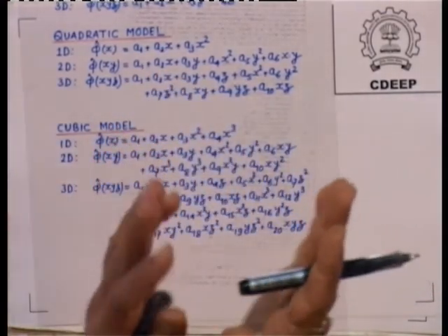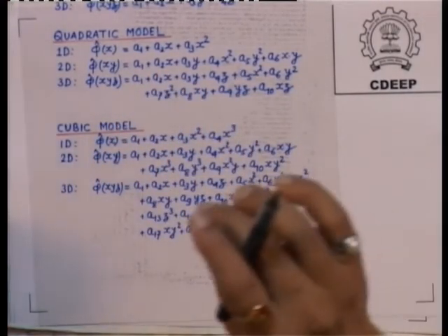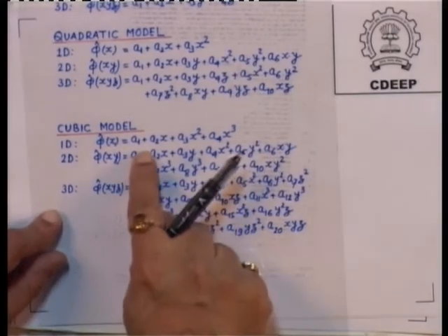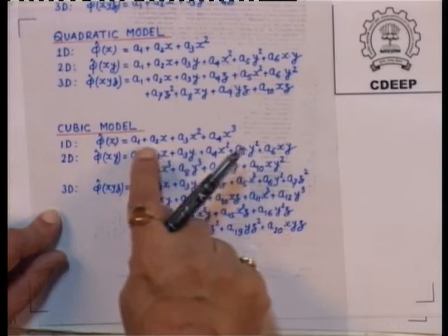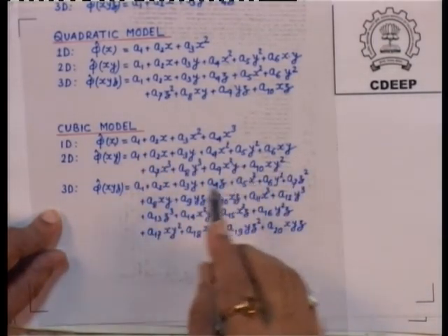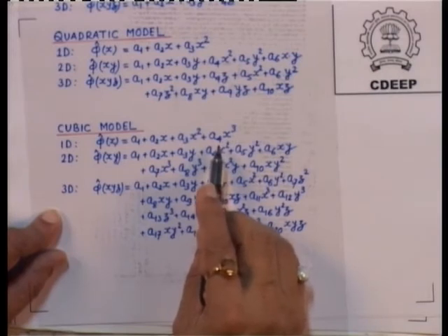These terms are taken such that this basis function or interpolation function is isotropic. It must be symmetric. You don't take x square, x cube, leaving y equal to only y square. If it is y square, you must take y square, x square and xy from the Pascal triangle or Pascal tetrahedron.